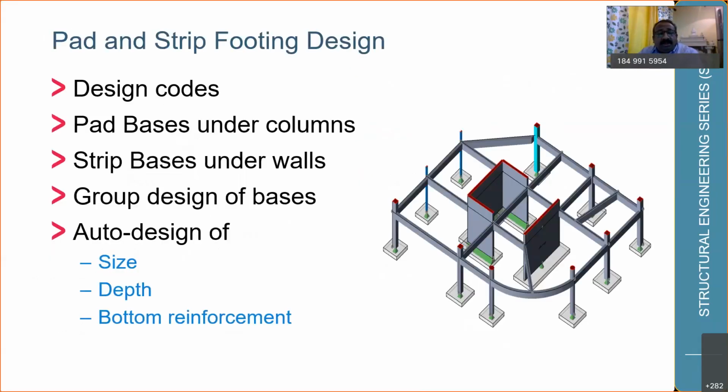And coming to the foundation designs, the different types of foundations and the foundation designs are automated, and it does the auto design of the pad footing or the strip footing, or the piles or the pile cap. So size, depth, and bottom reinforcements are automated, and as per the standards of practice, it does the design. They're all automated, and as I said, most of the tools I have seen have one single interface, where I can see the beam, column, slab, shear walls, and all the elements in one single window. One can complete all these activities, starting from the analysis and design and detailing also.